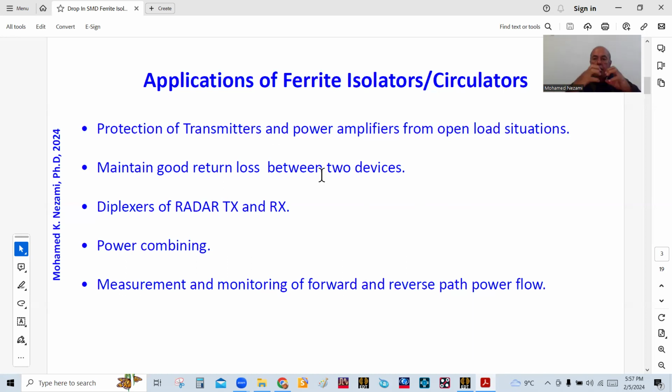So you've isolated these devices, because if you had a device designed separately and another device designed separately, once you interconnect them, they interact and they're not matched anymore. So you get a very bad ripple or reflections and so forth. One of the ways to go around this is you can put an isolator and it will completely isolate the loading from the interaction of the output impedance and the input impedance of the following system, if you can afford it, of course.